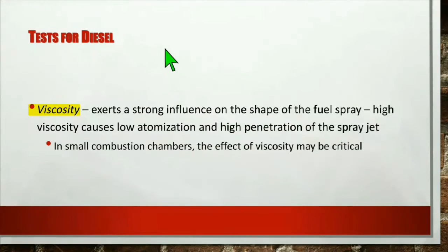Tests for diesel. Viscosity exerts a strong influence on the shape of the fuel spray. High viscosity causes low atomization and high penetration of the spray jet. In small combustion chambers, the effect of viscosity may be critical.